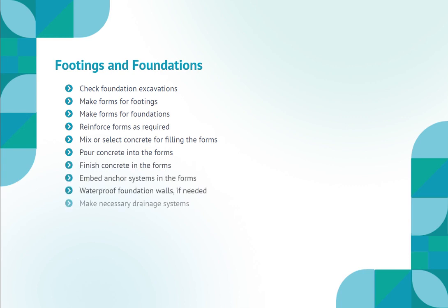Mix or select concrete for filling the forms. Pour concrete into the forms. Finish concrete in the forms. Embed anchor systems in the forms. Waterproof foundation walls, if needed. Make necessary drainage systems.